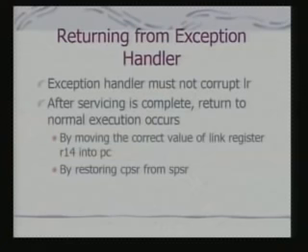It implies that before I actually return from the exception handler, I need to correct the value stored in LR so that I come back to the correct instruction which is to be executed. And I have told you that all these exceptions have associated with them a vector, that is a memory location. That location is accessed for getting the instruction for the handler. We go into the handler, and when I have completed servicing of the interrupt, I come back from the handler.